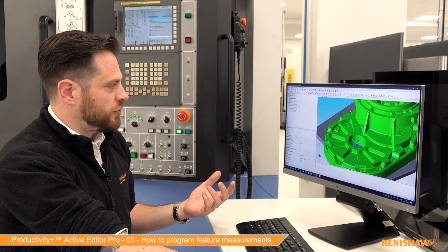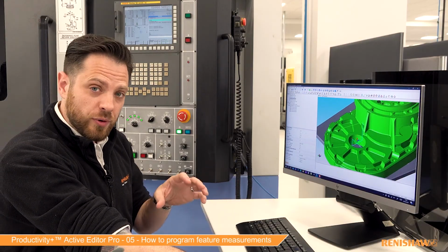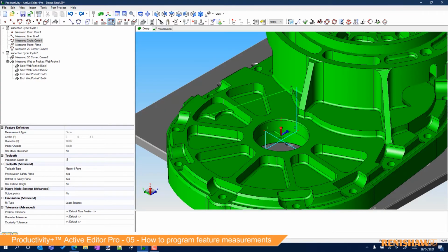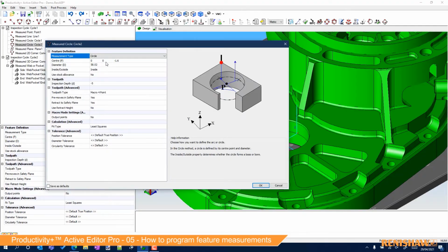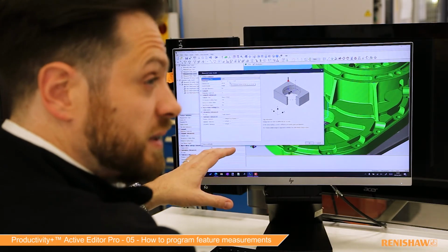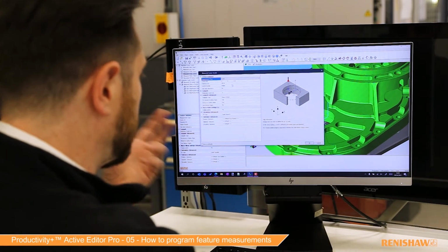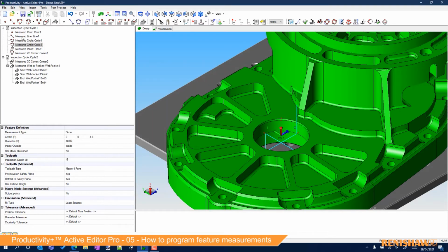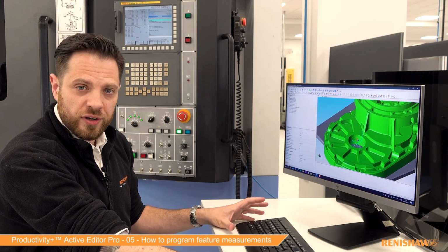Now, if this was a basic statement where it's not programmed from CAD, so what we can do is actually program one. So I'm going to choose a basic statement. Here is the information that we can type in. We can type in ourselves the position, the size, all of those things, and we hit OK. Okay, so this circle is a basic statement. It's not tied to the model.